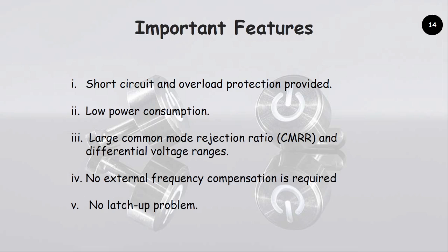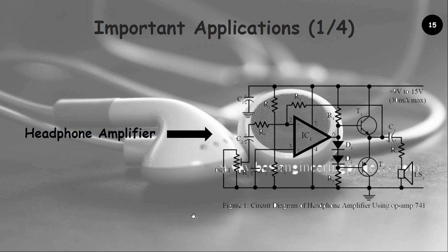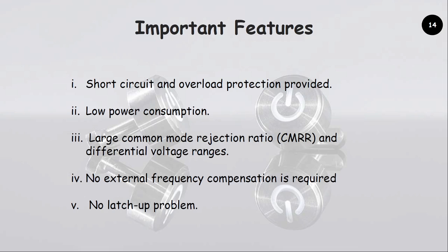Now the important features. Short circuit and overload protection is provided. Low power consumption. Large CMRR and differential voltage range. No external frequency compensation is required. No latch up problem. These are some features of this operational amplifier.